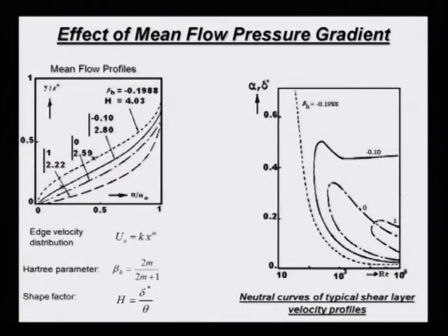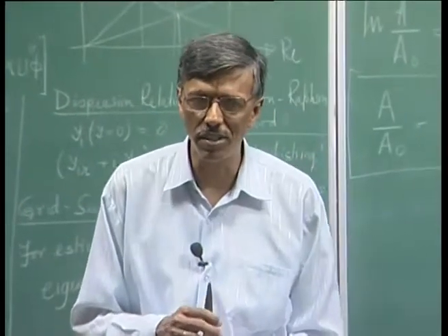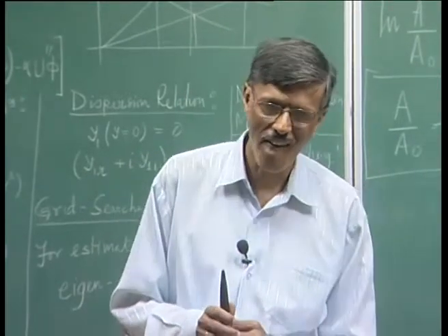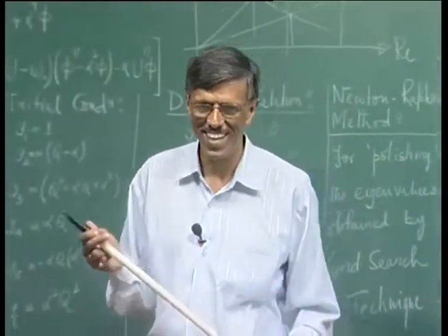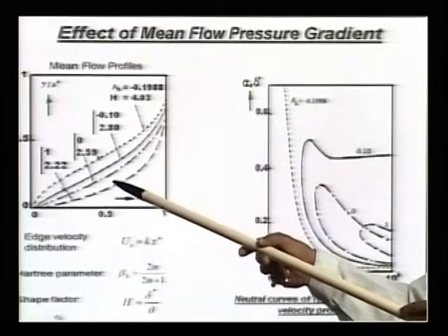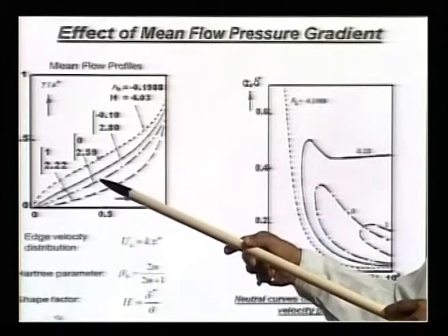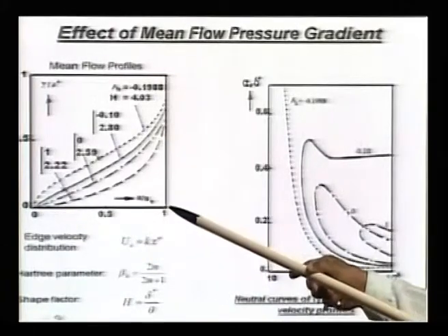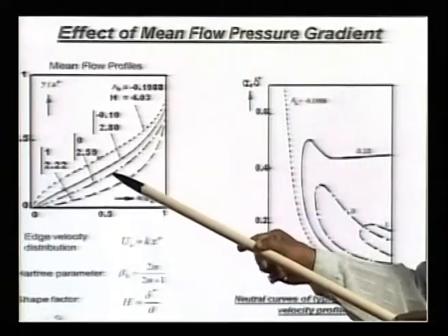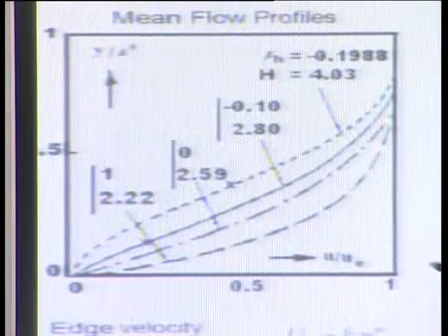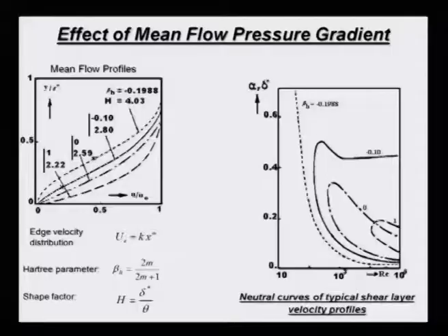2.8. So, should h increase or decrease for adverse pressure gradient? You look at the velocity profile that has been drawn here. If u was equal to ue, then I would have had the profile straight away here at 1. So, compared to that, this curve is displaced upwards. So, it has more mass defect, right, and then what happens?